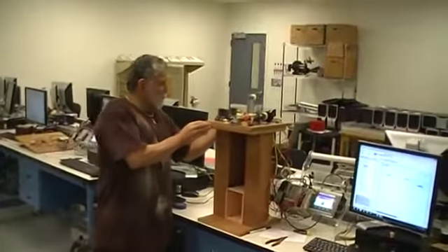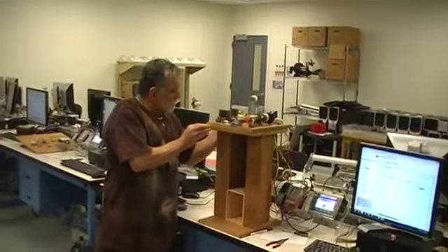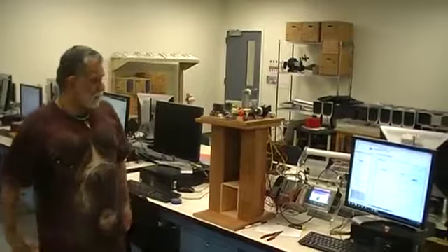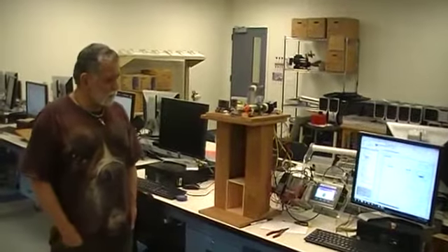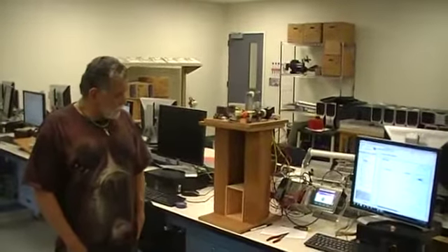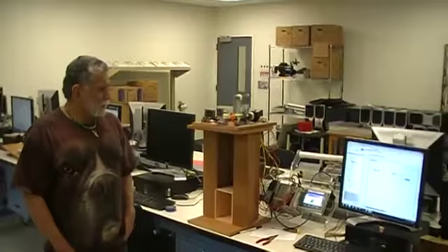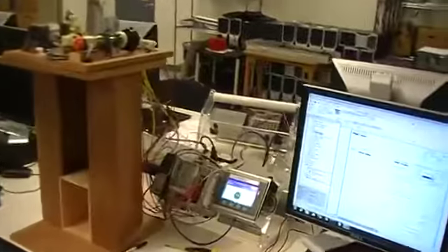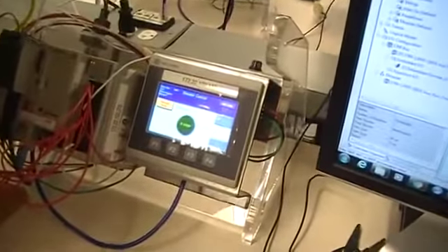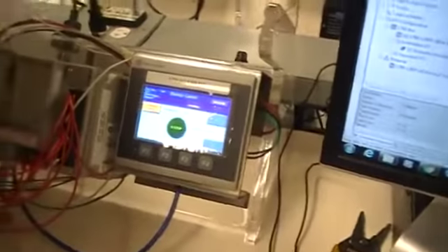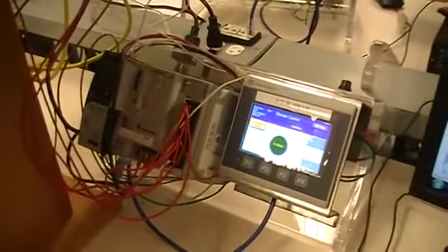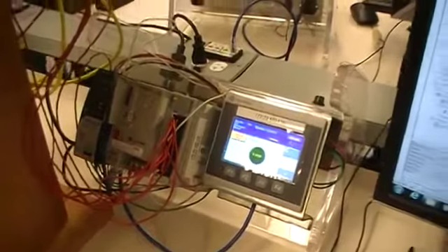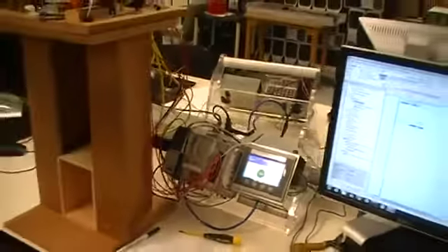My name's Jose Rios. I'm in FMT 122 with Art, and we have a project that we have to propose and introduce into the class. So utilizing a touch panel, an Allen Bradley T4T PanelView and a CompactLogix L24ER processor, I went ahead and built an elevator.